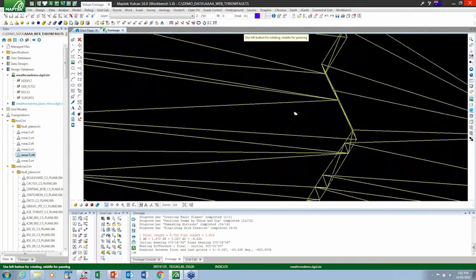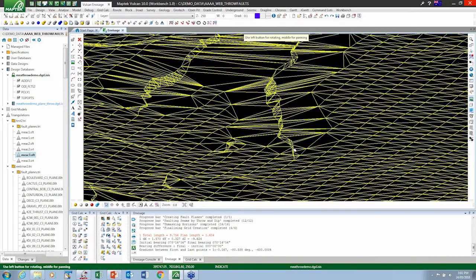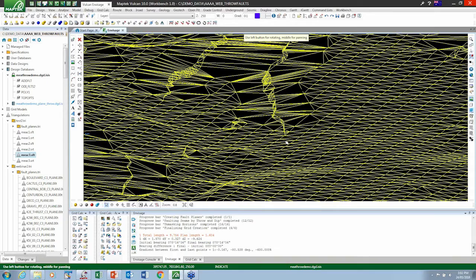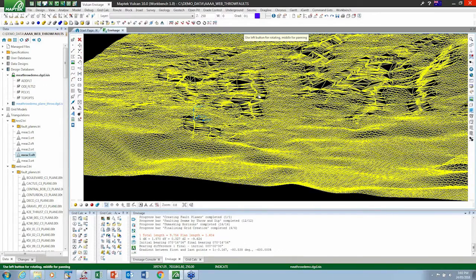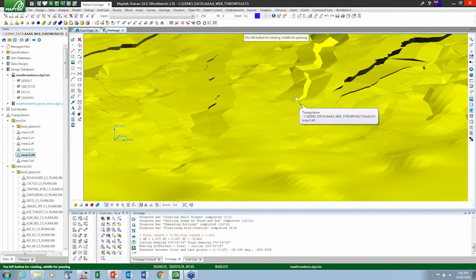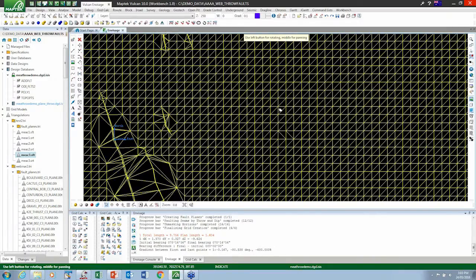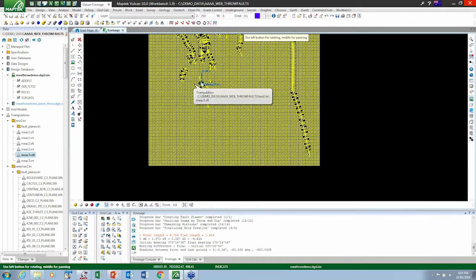This one here next to it is another reverse fault. You'll see that this is a normal one petering out to zero throw here. So it's a single surface with the faults imposed into it, and also that whole idea of the zone of influence, or the width of influence of the fault, you can sort of see here, because this is where the fault has been imposed into the surface.